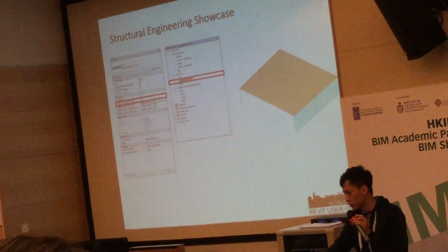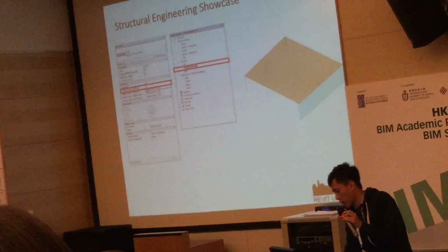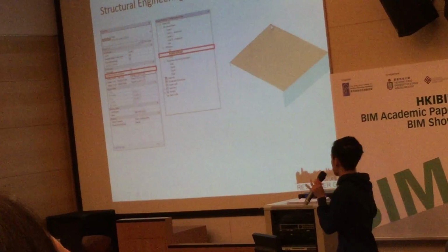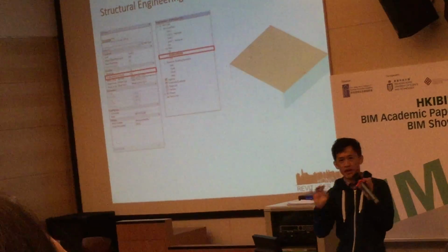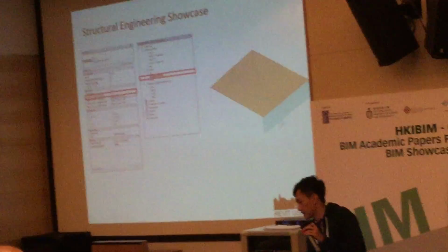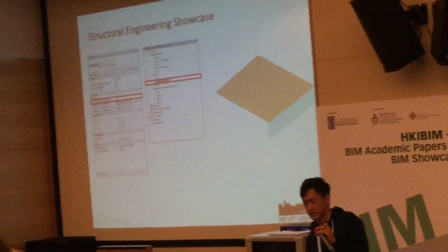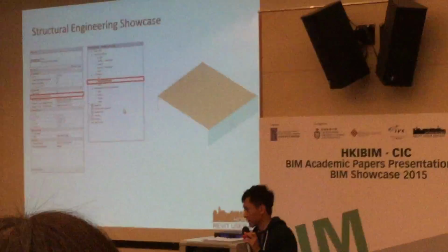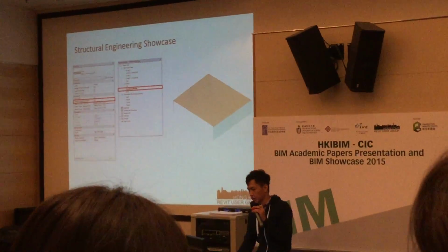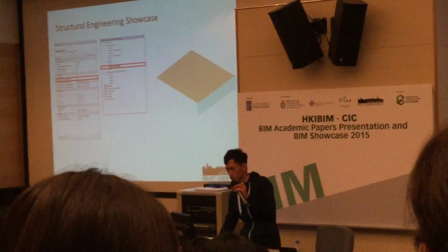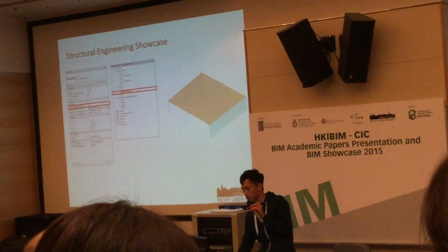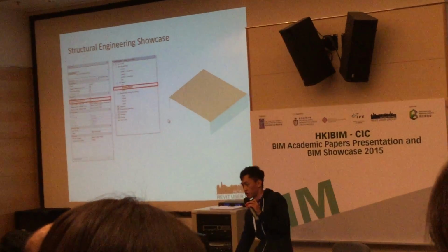So in your analytical model, you have these lines, I call them nodes and elements. These are the lines there, these are the structural members. For example, that line represents a beam. These plates are walls, if you aren't structural engineers. So basically, if you're building a structural model, you can decide which elements in Revit to be used for your analytical model. So you have this tick box. For example, you don't need that column. Highlight that, untick it, and you don't need to export it.